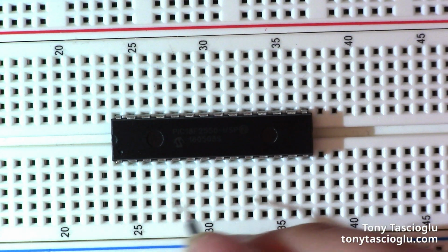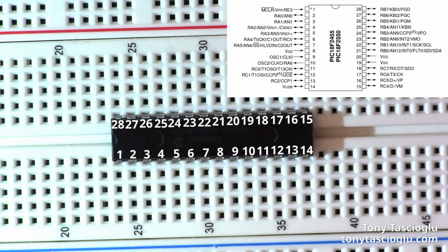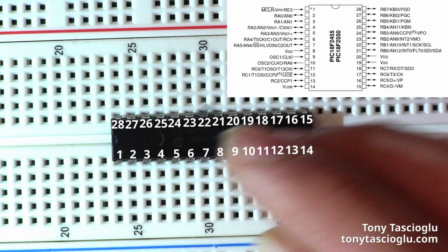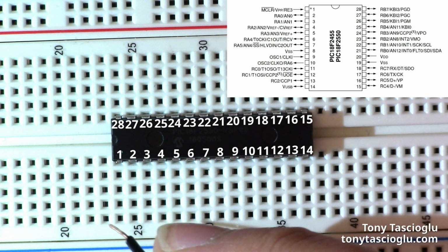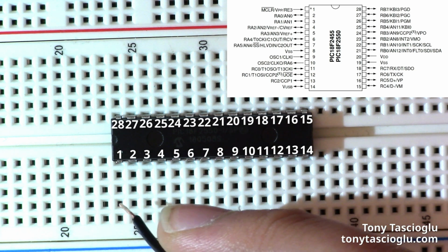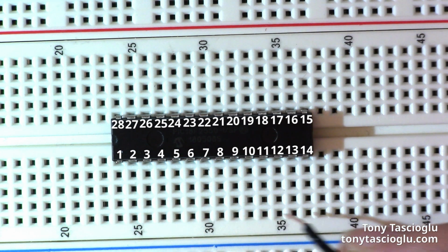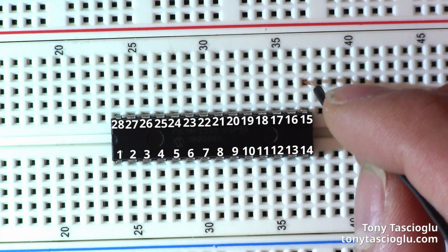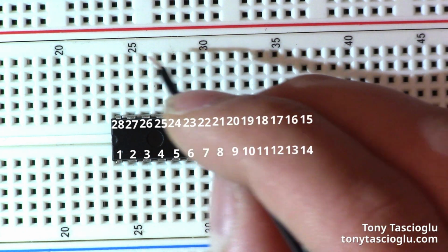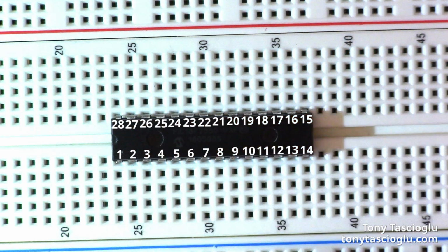To easily match the pins on your IC to the pins on a pinout on a datasheet, there are a couple of guide tricks that you can use. This 18F2550 is a 28-pin chip. Now, the way that IC's pins are usually numbered, you start on this bottom left corner with pin 1, and this goes all the way along the bottom row up to pin 14 in this case. Then you loop around counterclockwise, start again at pin 15, all the way up until the other end where you end at pin 28 in this case.